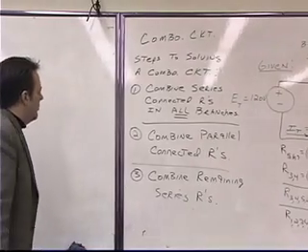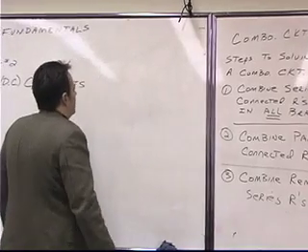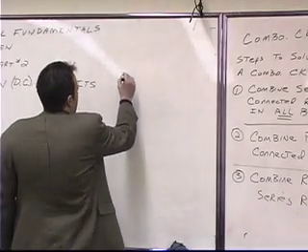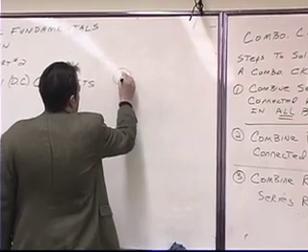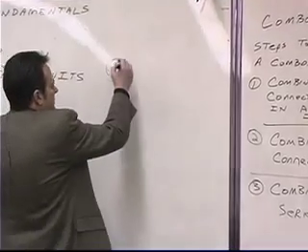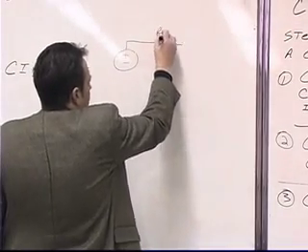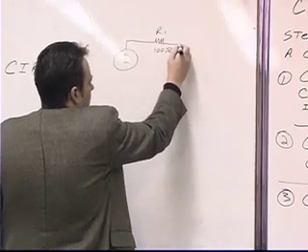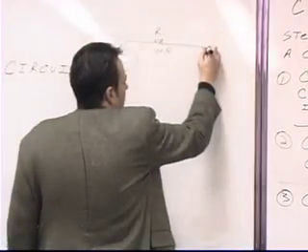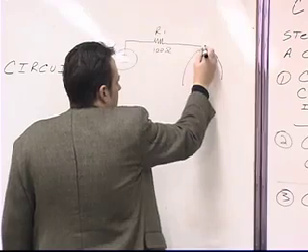Now, another thing that I want to point out is the topology, or the way that circuits can be drawn, which sometimes can be very confusing. But really can be simplified by just looking at them and asking yourself how Kirchhoff's current laws apply. Let's say that you were given a circuit that looked like this. You had a voltage source and a resistor, so this is resistor 1, it's 100 ohms. Okay? And then this came into a node, or a point. And then this point right here went this way, went straight down, went over this way, and went over this way.